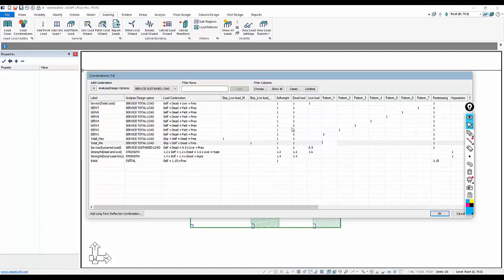So in other words, we don't overlap and envelope the contour results graphically. So this is how we would set up the model for the purpose of evaluating contour results. It's not only deflections, it could be moment XX, moment YY, in-plane axial forces or stresses, and so on.